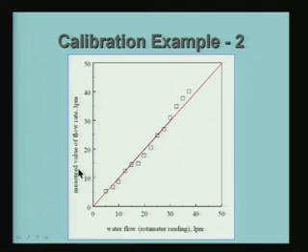The measured value, which is measured using the absolute method I talked about, collecting a certain volume of the liquid over a particular amount of time, is compared with the reading indicated on the rotameter, and you can see that there is more or less a good comparison, but of course, there are some variations which can be used as calibration information, or you can use a correction factor. As you can see here, for example, the actual measured reading is smaller than that indicated by the rotameter, and here it is the opposite. So, the error is both positive and negative in this particular case.